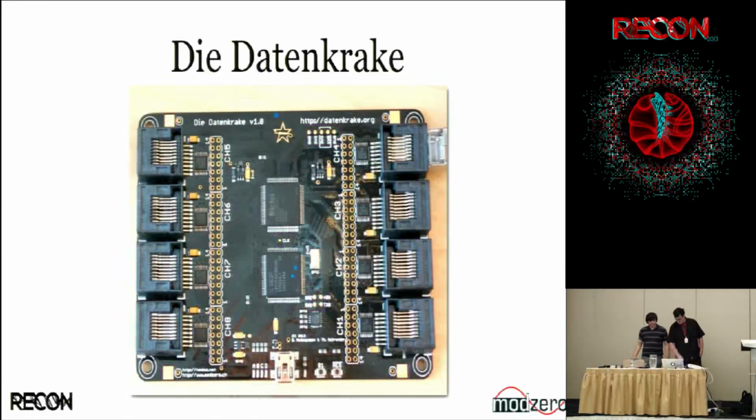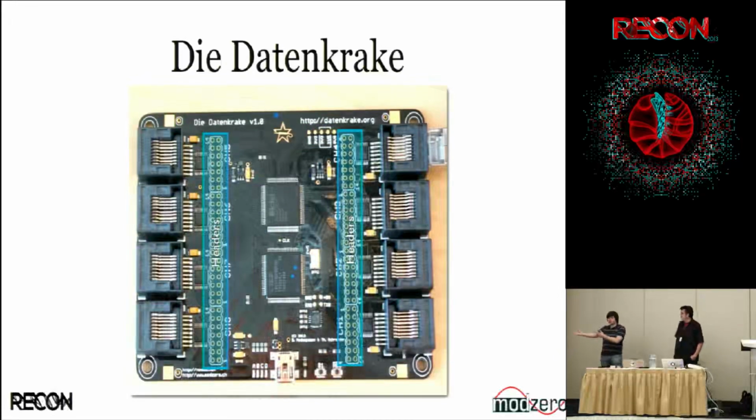Okay? So yeah, and the last one's the most important part, at least for me. I want to have access to all of the signals. And on these headers, on the side where we have the ARM and the FPGA, you have the unterminated signals. So basically whatever the FPGA is spitting out. And on the right side, or right and left, so the outside world facing the RJ45s, you have terminated signals. But again, as we said before, you can disable the buffers and do something custom.